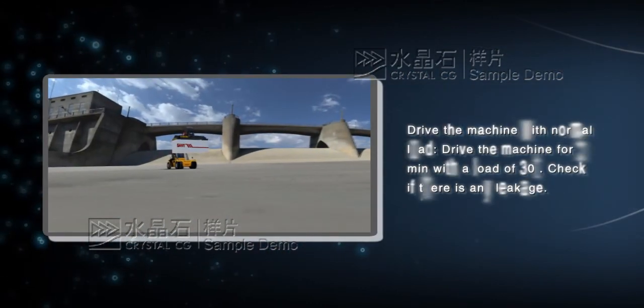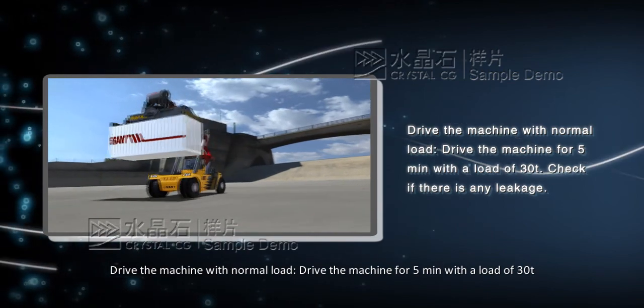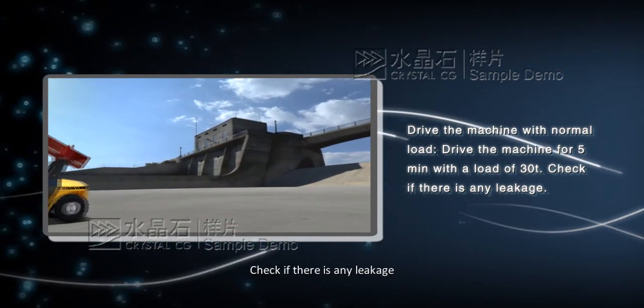Check working state. Drive the machine with normal load. Drive the machine for 5 minutes with a load of 30 tons. Check if there's any leakage.